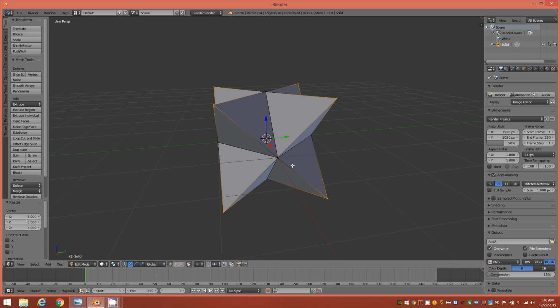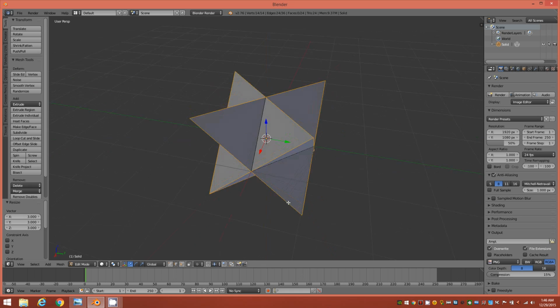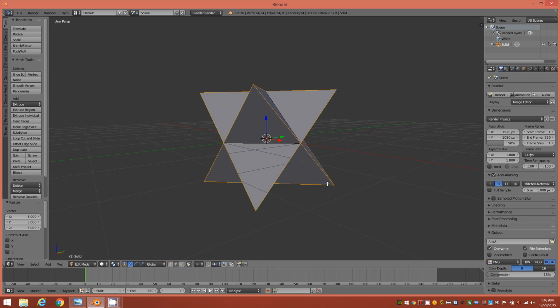So from here, with these points still selected, we're going to hold down Control, and then down here in the panel where you have some of your settings, you'll see these three buttons. Holding down Control, switch to the Edge mode by clicking on the button. This won't work any other way but choosing the button down here in the icon. So holding Control, just click the icon and it will switch your selection over to these particular edges.